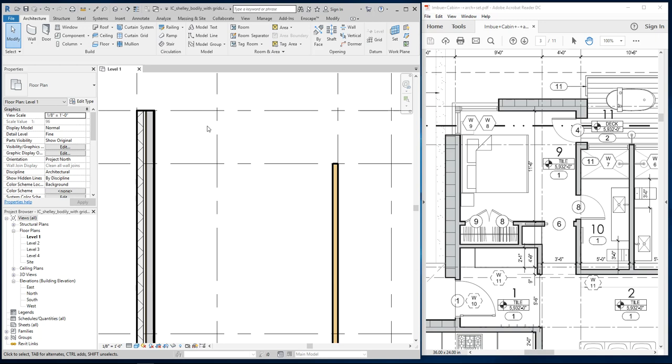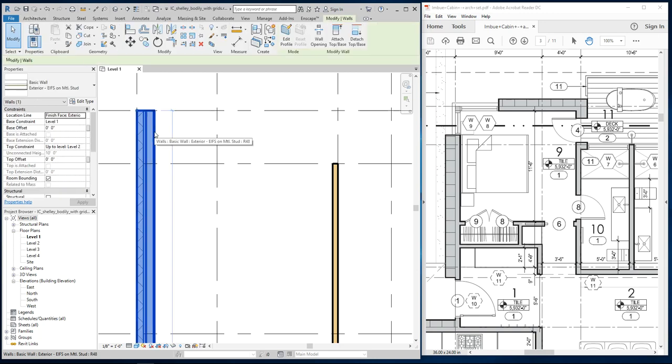reiterate in Revit that when you're creating a new type of something, there's no new wall type button, right? There's no new door type button. There's no new window type button, right? Essentially, the way Revit works is that you take something that's already existing and that is somewhat defined close to what you want to generate. You're going to take that existing object, duplicate it, rename it, redefine it, and then use it, all right? And the idea behind taking something that's already existing and redefining it is, I think, supposed to be less work for you, essentially, right?